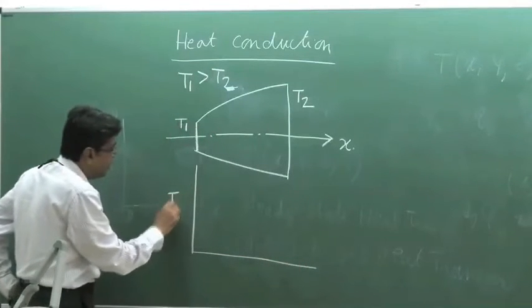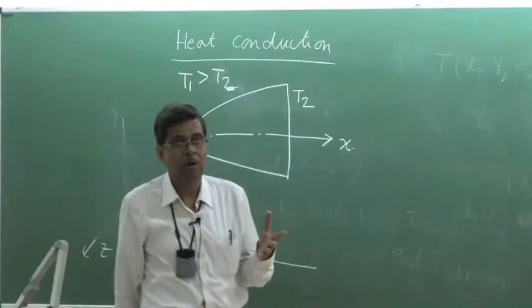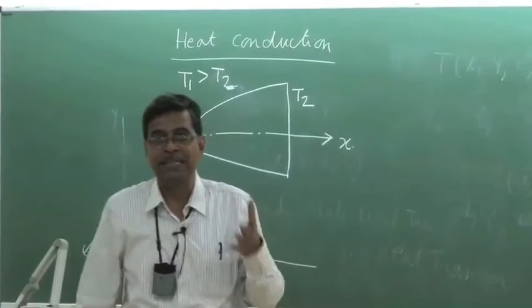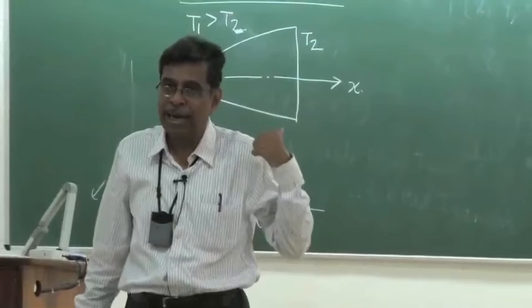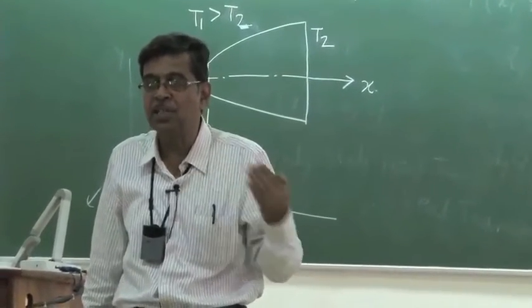Will it be linear? Will the temperature variation at steady state, one dimensional, will it be linear? No, because area is not constant.